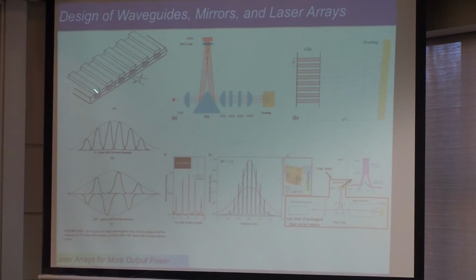That's really because of inherent limitations of each laser. For example, each semiconductor laser diode would output probably a few tens of milliwatts or maybe 100 milliwatts. But then you can always take many of them, have an array of them, and combine them. Now the combining of the output of many laser arrays is not a trivial task because each laser has its own coherence, its own phase, and all that sort of thing. But the problem is very similar to power combining of an antenna.